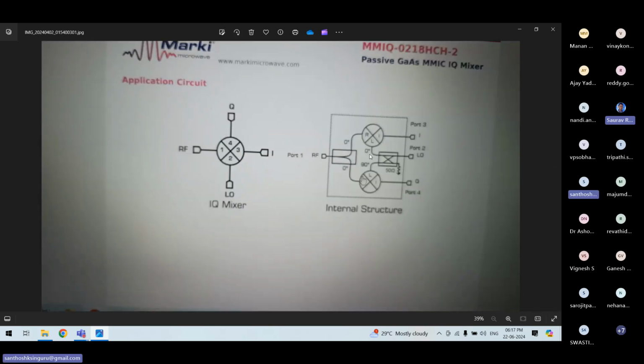See, generally what mixers do is generate different frequency signals, not phase. We take the carrier signal and some lower frequency signal like I and Q. At the output you will have omega c plus omega n and omega c minus omega n, so you get a carrier frequency shift, but not a phase shift.